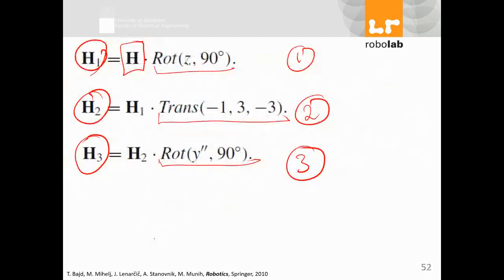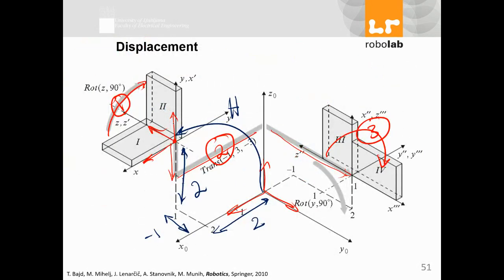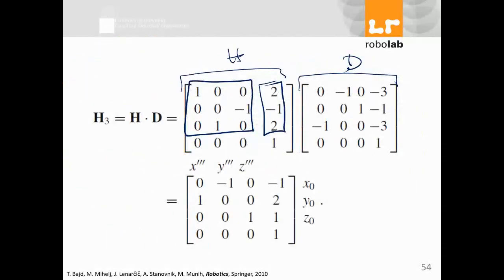if you look at these two coordinate systems, this second one, the top one, this one and this one, you see it's not only a translational move, it has also been rotated. You see X, you see Y, you see Z, meaning it's rotated around X. It's rotated around X by 90 degrees counterclockwise. That's why you have rotation around X.